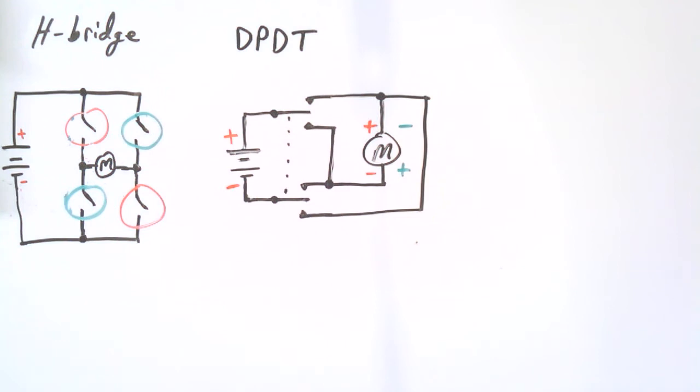First, you figure out what you want to do, sketch it out, then take a step back, look at your sketch. Make sure that the sketch works. Make sure as you look at it, you can see the different actions for the switch, the different scenarios. Make sure they all work out, that you didn't cause a short somewhere, and then follow the wiring that you've drawn when you're actually doing the wiring.